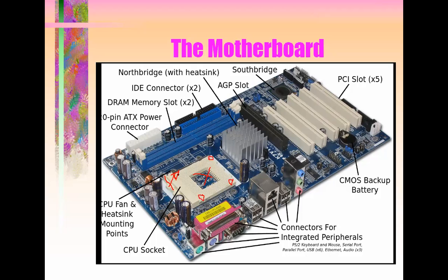So why do they put this one? So that if you sit it wrongly, no pin will get into the holes. Until you sit it properly, then it will get in the holes. So once you sit it properly, then you just push down that jack, then the CPU will be fixed into position. So this mechanism is so that the CPU can be plugged in without exerting pressure on the CPU, and second, without touching the top of the CPU, because if you touch the top of the CPU, you might cause electrostatic electricity, and that will also affect your CPU. So that's basically the CPU socket.